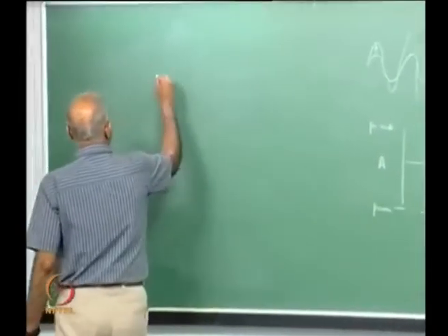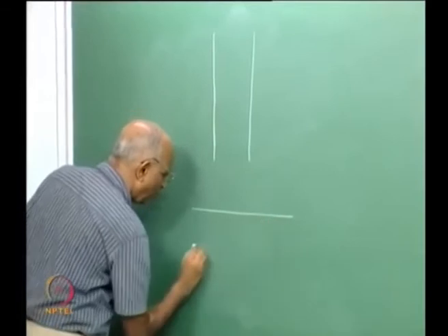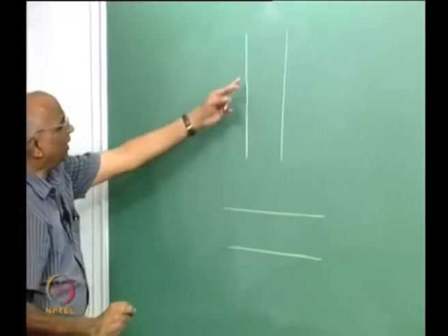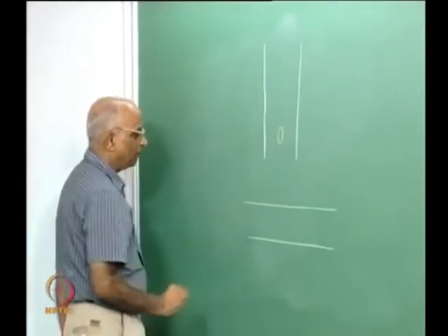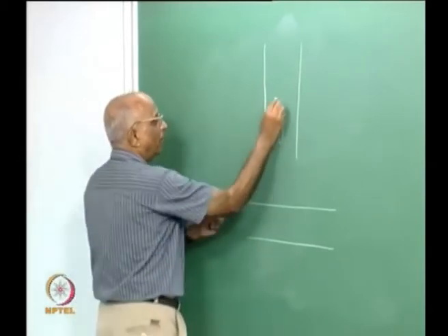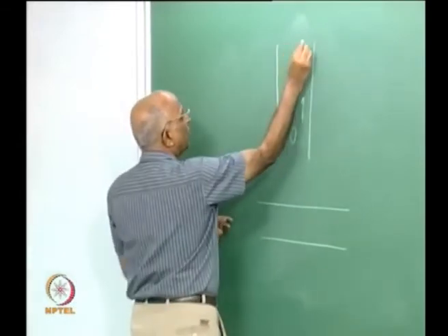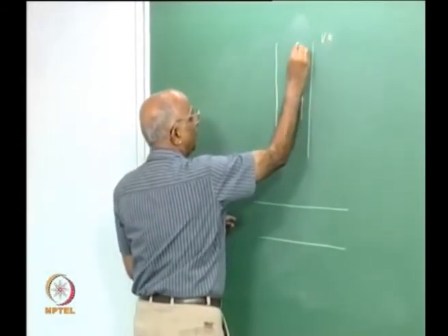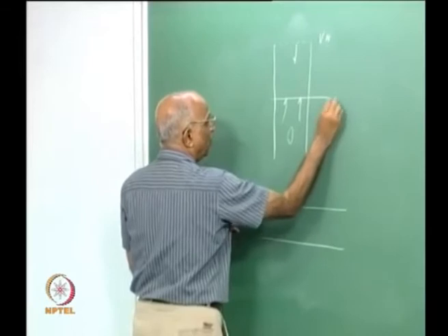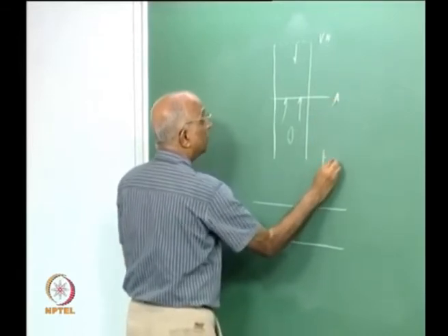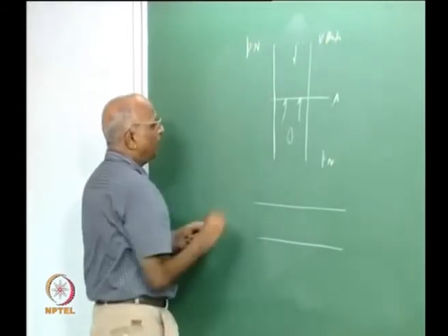We found that the tube in the vertical condition made lot of noise, whereas in the tube which was in the horizontal direction also made some noise, but was not as high as in the vertical tube. What did we do? We put some heat source at some location. When I put some heat source, hot gases are convected up. Hot gases are convected up, they meet this boundary wherein I have the velocity node, it gets reflected, I get something like a pressure antinode over here, I get a pressure node here, I get a velocity antinode here, pressure node over here. And what is happening?